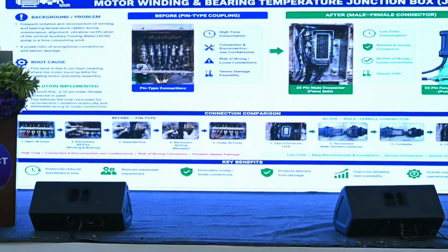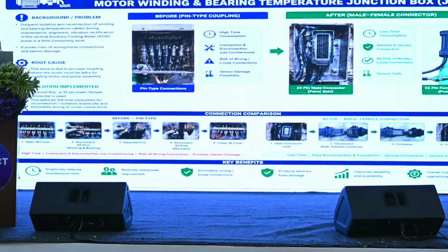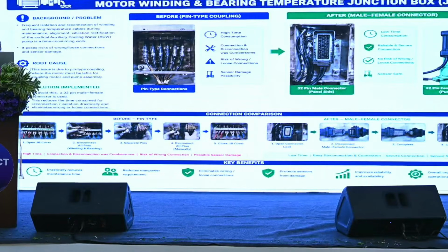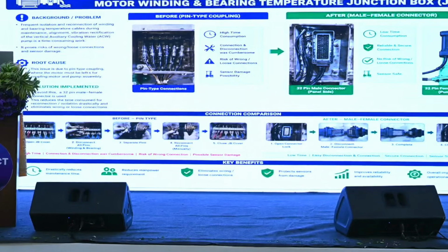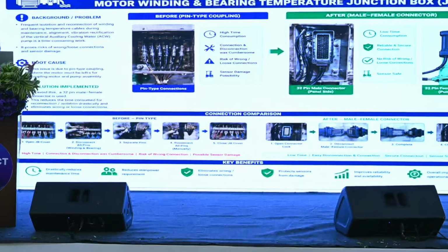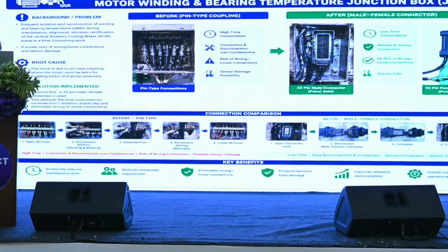Next, we know that in maintenance, the instrumentation, mechanical and electrical maintenance are like a sandwich. First, instrumentation people have to remove the cable, then the mechanical person does the work, then the electrical person does the work. Likewise, in our plant the motors are vertically mounted. So for any work taken up by mechanical or electrical maintenance with respect to the motor or gearbox, first the instrumentation cables need to be removed, the cables related to bearing and winding temperature RTDs. Whenever they wanted to take up maintenance, they would ask us to remove them. Once the work is done, we have to put them back.